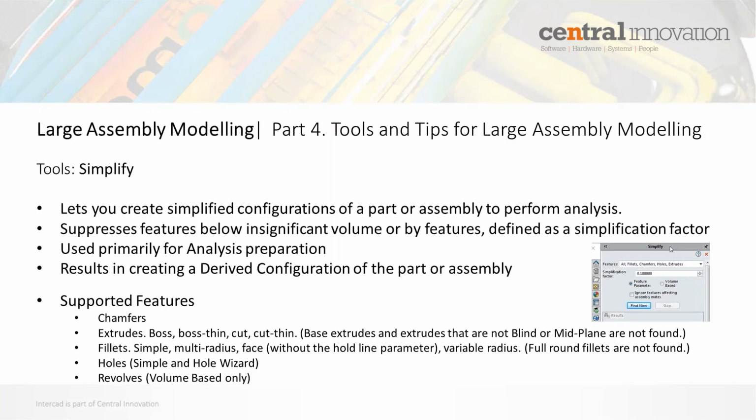And I guess the only other downside to this is that it doesn't support assembly features. So if you've got assembly cuts or extrudes through the assembly model, then they aren't actually supported in the Simplify tool. But it's another option if you need to reduce the amount of detail quickly in a SolidWorks large assembly.